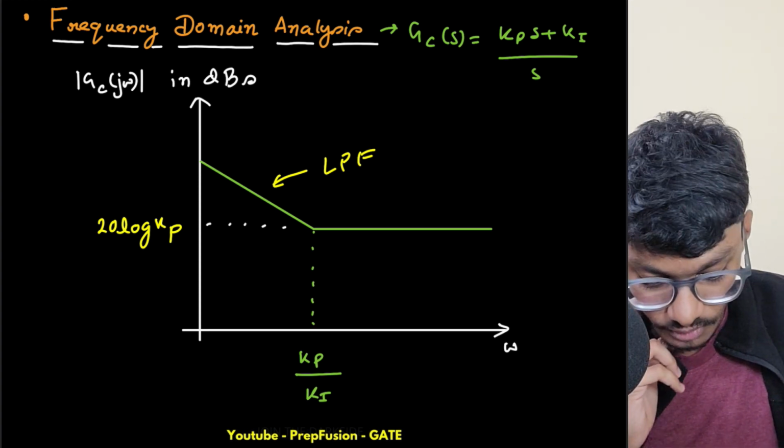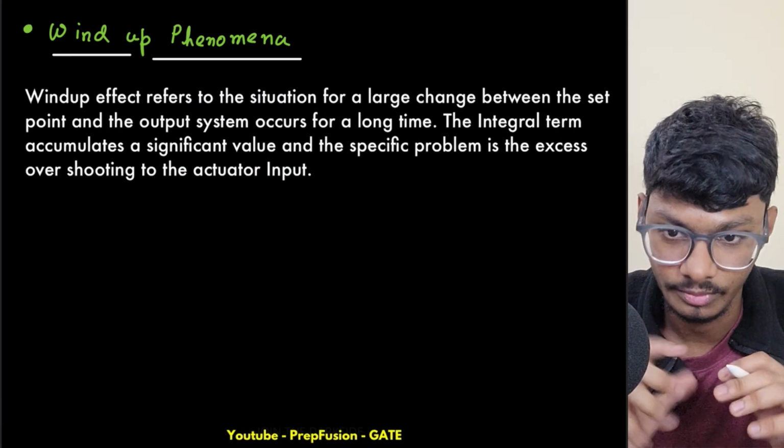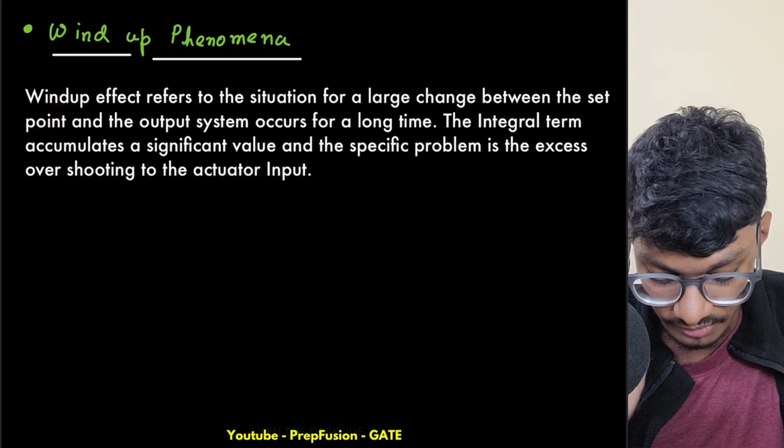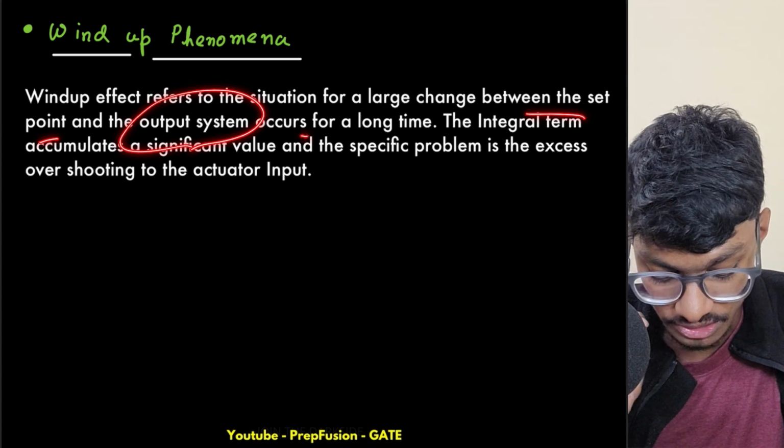So one thing is that I was talking about the wind up phenomena. So what is wind up phenomena? Wind up phenomena or wind up effect refers to the situation where a large change between the set point and the output of the system occurs for a long time.